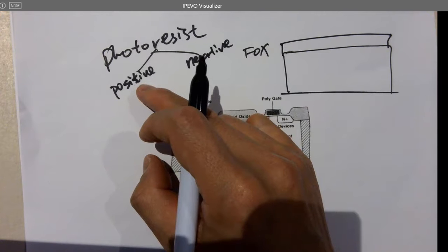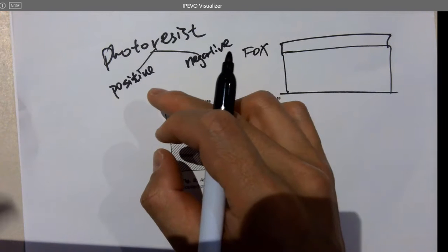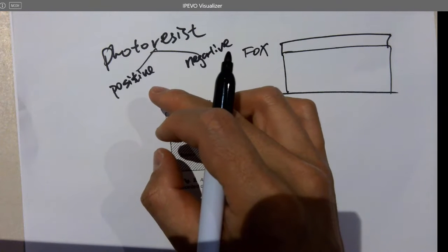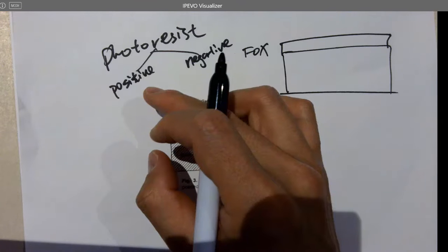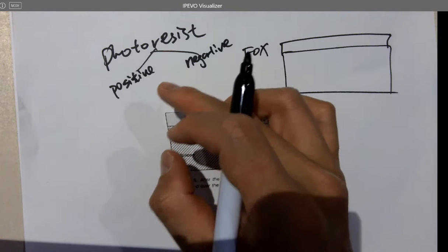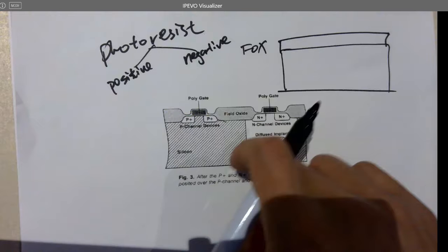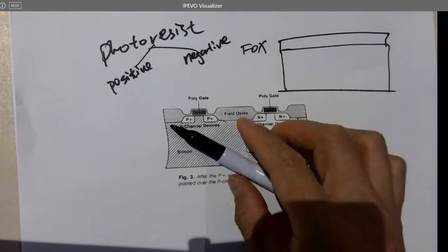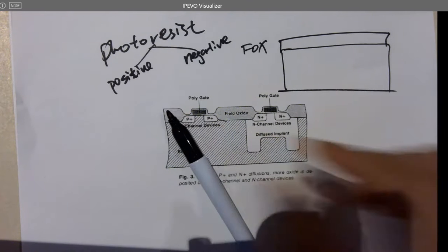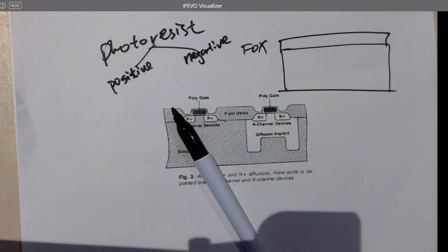That material is very photosensitive, especially to UV, ultraviolet. But also these lights also have UV component in there, not super strong UV, but you don't want to expose that wafer with a photoresist anywhere that has a UV component in the room. So that's why usually they use the orange color or orange light in the clean room.